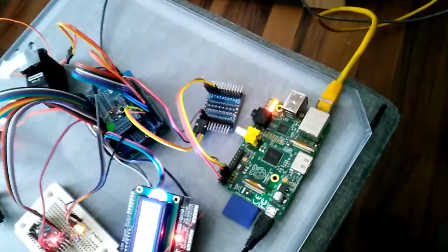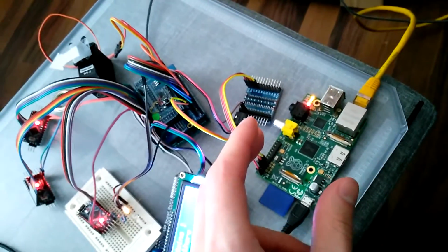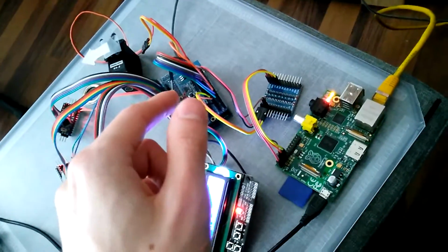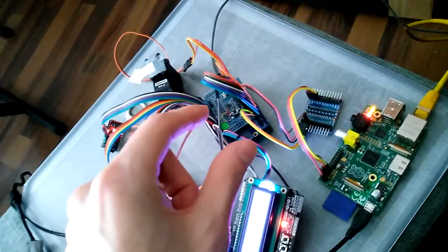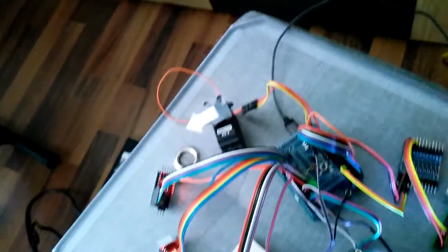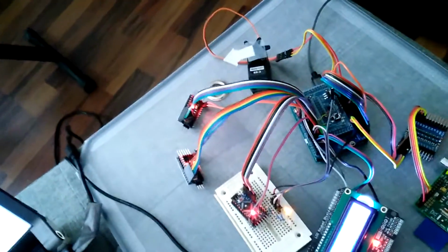The Raspberry Pi, every time it changes the wiring configuration, also sends out a UART message that tells the Arduino what angle to turn the servo. So the servo always points in the direction of the UART that is currently controlling the LCD.